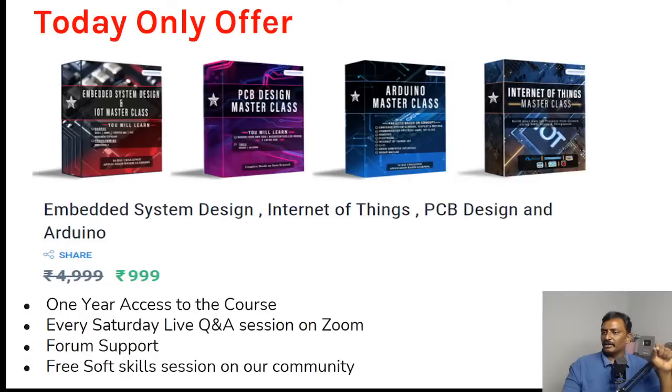What is a controller? Sushma is asking. It's a microcontroller or a controller. It cannot do complex mathematical calculations. It could do only control applications, logic kind of applications, like a simple door lock. Whereas microprocessors and DSP processors are meant for complex mathematical calculations. But if you check the latest microcontrollers like the Cortex M4 series, they all have DSP capability. They don't want to miss the market, so they also come up with mathematical capability. The latest version of the Cortex M4 series can do DSP processing, not at a high end, but for low end applications.